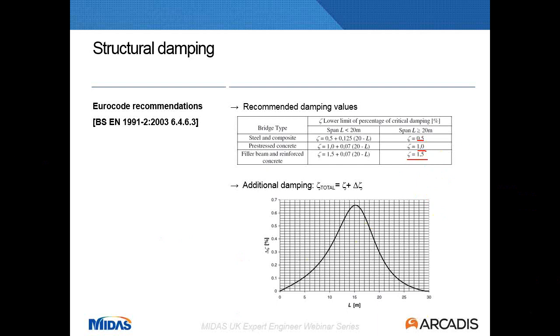You spoke about underestimating the time step. Can you speak about overestimating it? I understand that overestimating it is like saying, I'm going to be safe, so I'm going to use 0.1 milliseconds for my analysis. Well, you can use 0.1 or even less than that. The only problem is the smaller the time step, the longer it will take to run the analysis, and the size of your output files is going to increase exponentially. So you have to be careful.